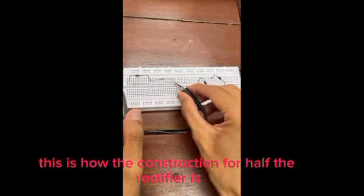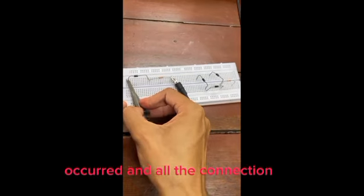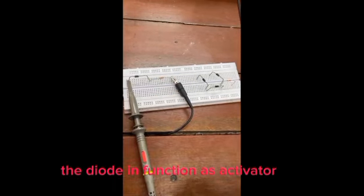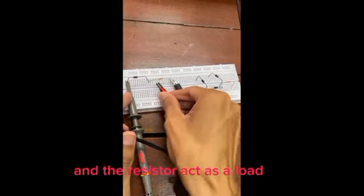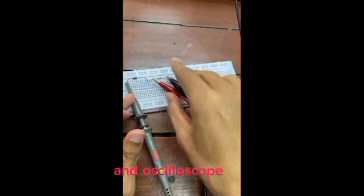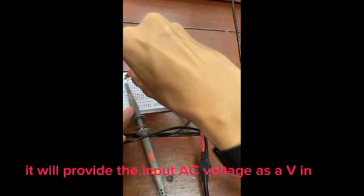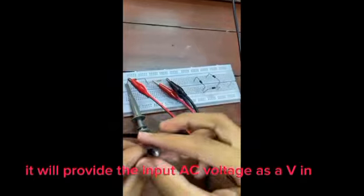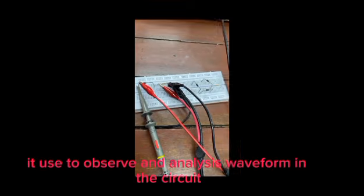This is how the construction of the half-wave rectifier circuit and all the connections look. The diode functions as the rectifier and the resistor acts as a load. All the connections come from the power supply and oscilloscope. The power supply I use is a function generator. It will provide the input AC voltage as Vin. And the oscilloscope is used to observe and analyze the waveform in the circuit.